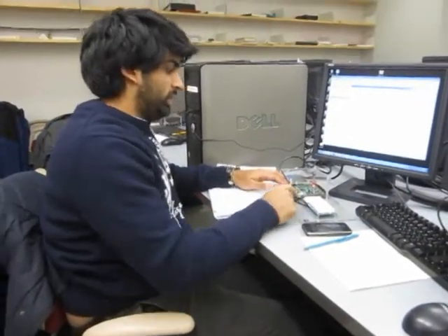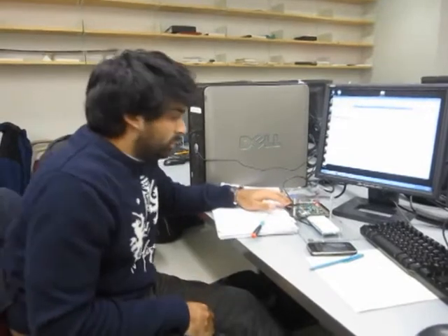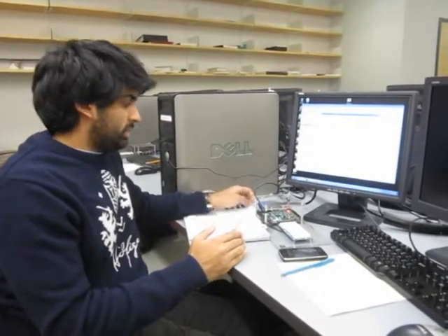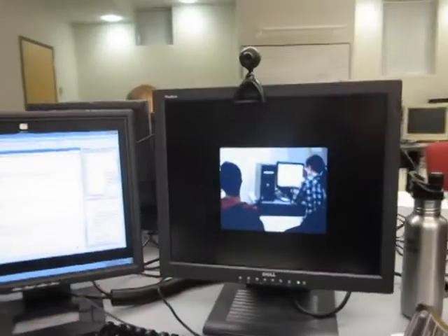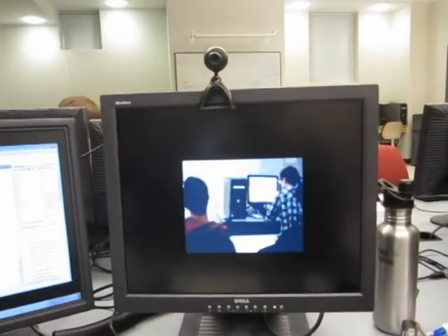Once the signal is received by the FPGA over the UART, it is loaded into the block RAM, where it is stored until the image is fully transferred. After that, it is sent over VGA to our monitor, where you can view the live streaming video.